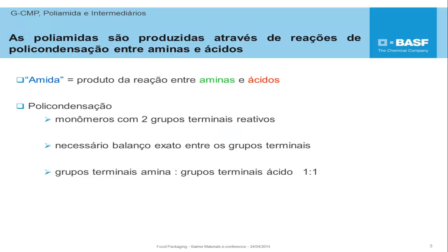Slide 3. Polyamides, like other plastics materials, are obtained through a chemical reaction between the monomers. These molecules are units that are repeated. The reaction to obtain polyamides is the polycondensation reaction, that is different to other polymers like polyethylene that are produced by an addition reaction in which these monomers come together, as if they were train coaches. In the case of the polycondensation reaction, there is a reaction between groups of the monomer forming a small water or even acid molecule.